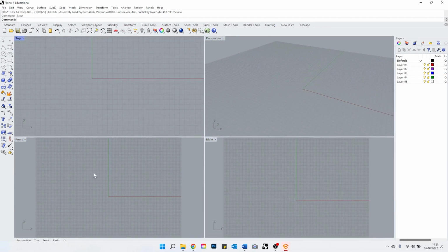You have your top, front, and right view, which represent your orthographic projections. So you're not going to have any perspective distortion if you produce any form of a drawing or a model in it. You're going to have your floor plan or top view, and you're also going to have your 2 side elevations. One from the front, one from the right, or if you want, you can always change it to, for example, back or left, and so on.